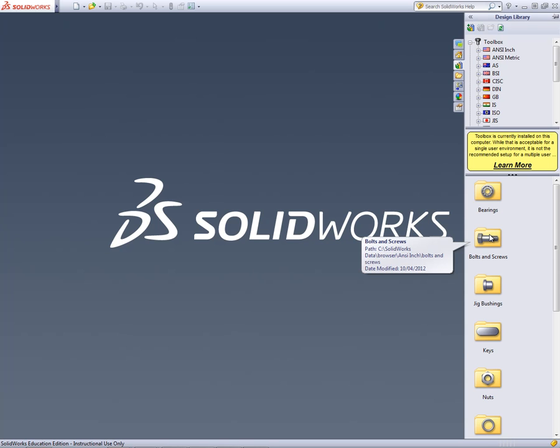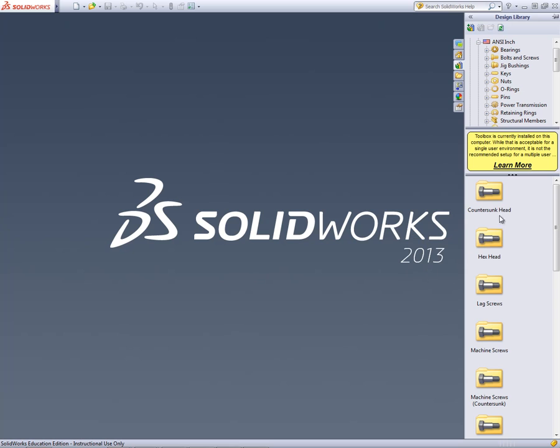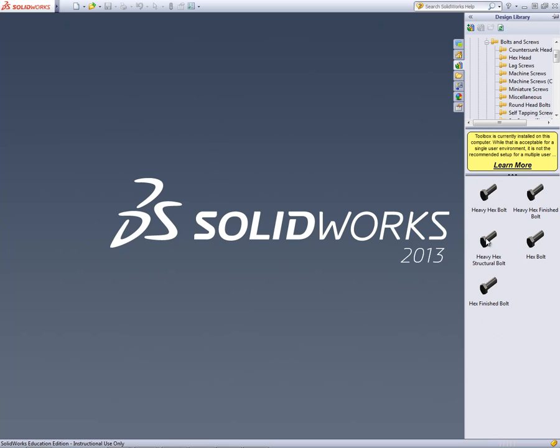These are pre-made or pre-designed parts that SolidWorks has had somebody draw, and so rather than somebody drawing their own nuts or bolts, you simply pull these out of the design library. So we'll double click on the bolts and screws, and we'll just pick a hex head, double click on hex head, and these are all the types of bolts that are available as hex head bolts. Now here, rather than double clicking, we simply right click and we left click on create part.